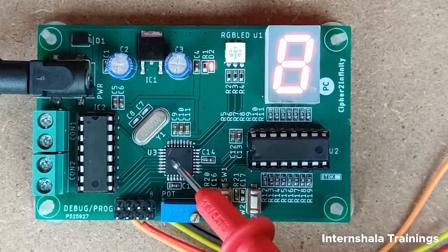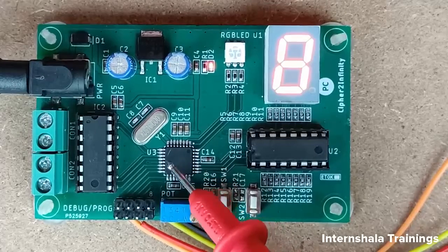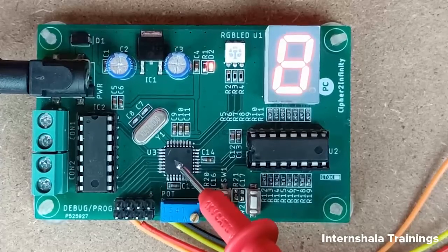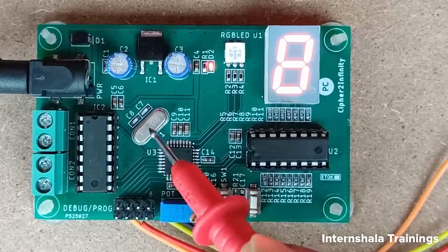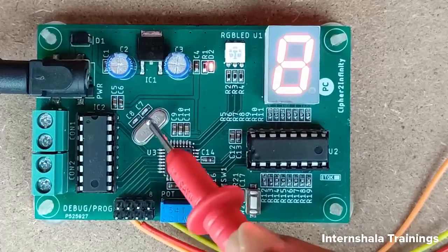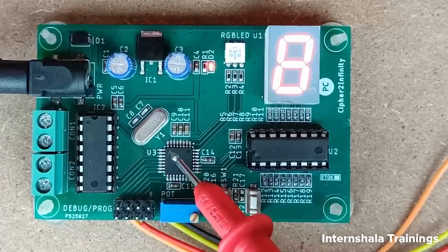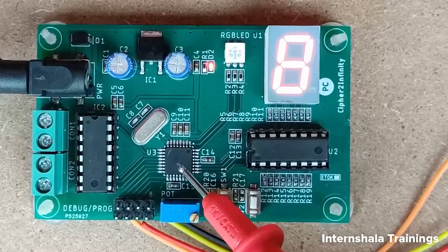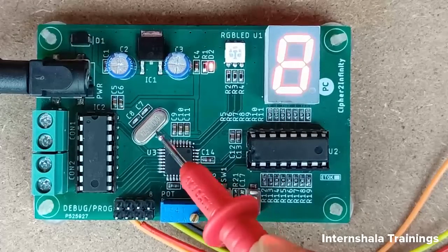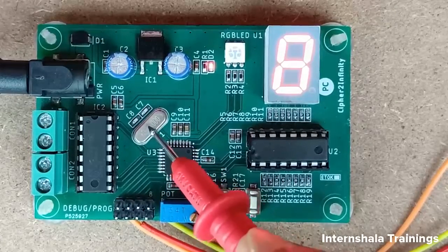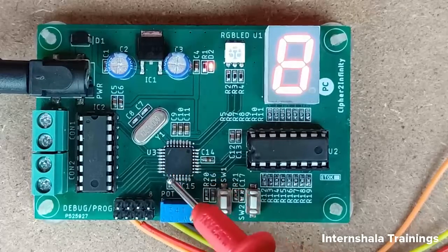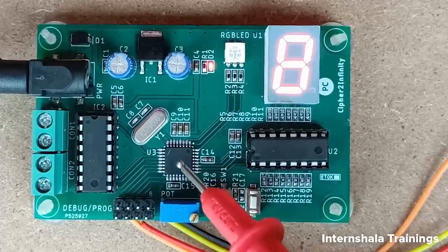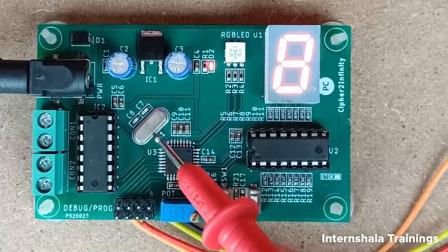After that, the fourth mistake that you should avoid is, once you have programmed the bootloader and the fuse bytes in the controller, you have to make sure that you connect this 16 megahertz crystal, or external crystal, to the crystal pins of the microcontroller. Otherwise, the controller will not work properly, or it will not boot up. Connecting this 16 megahertz crystal is very important, because while programming the fuse bytes, we told this controller to use the external crystal as a clock source.